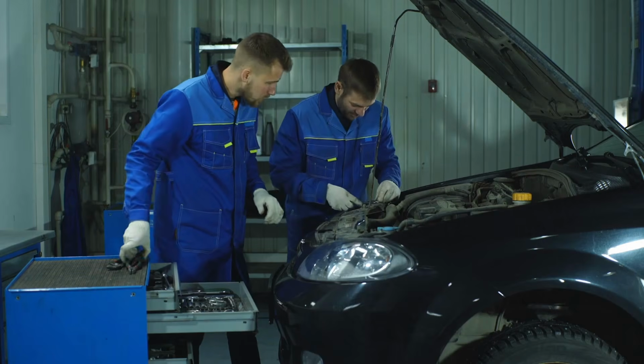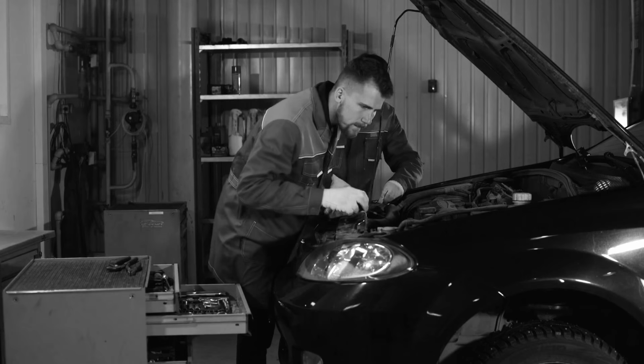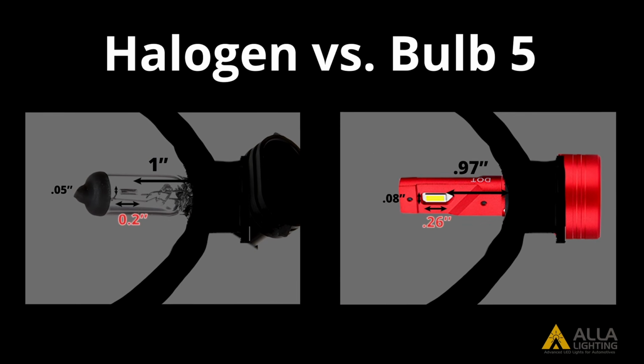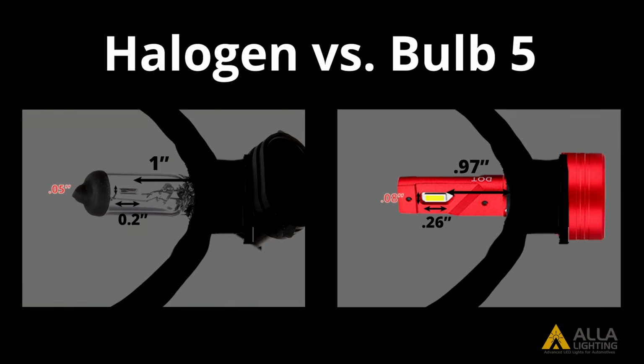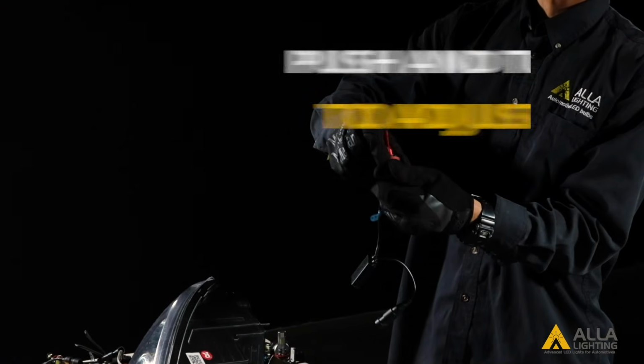How do you fix this? You can't fix the design defect, but you can avoid such products. When shopping for LED headlights, pay attention to the LED chips. Look for one that matches the stock filament most in both shape and relative location to the housing. To fix the beam adjustment, most LED headlights come with a removable or rotatable chuck.